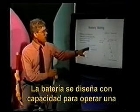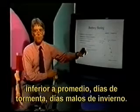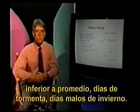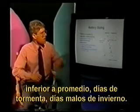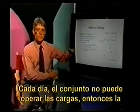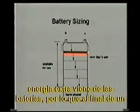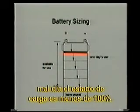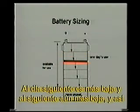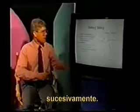A battery is sized to operate a load during a sequence of bad days where the insolation is below average, stormy days, bad wintry days. Each day, the array cannot operate the load, so extra energy is drawn from the battery, and the battery state of charge at the end of a bad day is less than 100%. The next day, it's even lower. The next day again, maybe it's even lower, and so on.